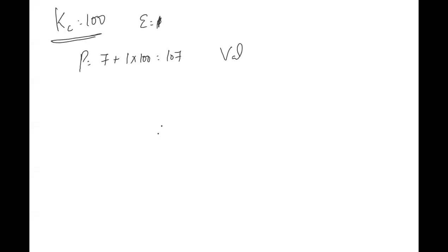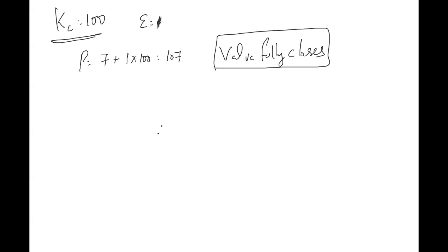Now suppose since Kc increases, the fastness increases. Somebody very optimistic, or very curious, has put Kc equal to 100, or even 1000. Then what happens? If my error is, let's say, 1, then the pressure signal is 7 psi plus 1 into 100, so it has become 107. The valve fully closes. This is an air to open type, or rather air to close type, because we need a fail open situation. No, this is an indirect type of valve.